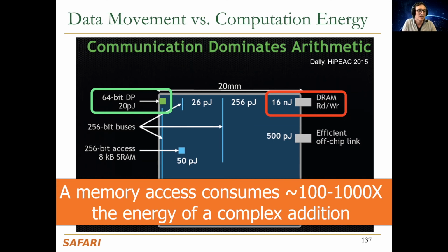As a result, you can see exactly the example architectures that I showed you, the Cerebras wafer scale engine. The goal is to bring computation and memory together as much as possible so that you don't go off chip, such that your AI accelerator becomes efficient. In Samsung's FIM-DRAM, function-in-memory DRAM, designed for AI applications, essentially the same goal in a different way. They design a memory chip that can do floating point multiply and accumulate operations, as opposed to doing those operations in the CPU. Similar to UPMEM architecture, right? Essentially the same idea in the end in different realizations. Okay, so keep that in mind.